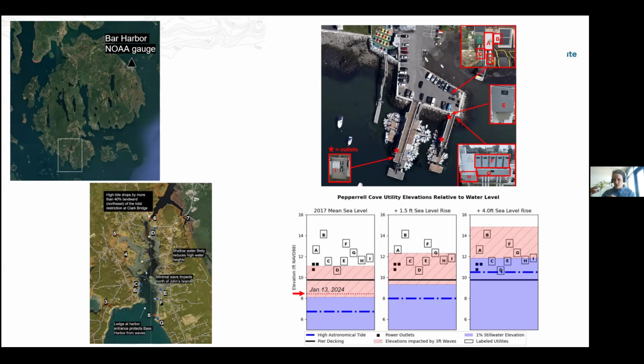We don't really have to worry about a Hurricane Sandy coming. So it's really great to use local knowledge and documentation of recent flood events to use as a design flood event in tandem with imperfect data sources that are out there. And that's what this is showing.